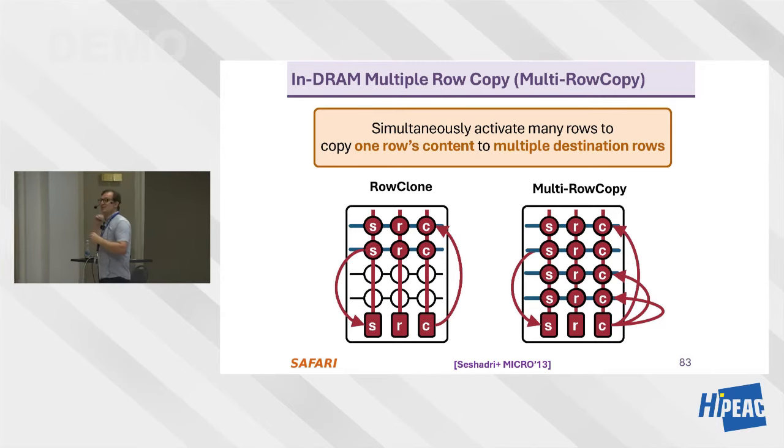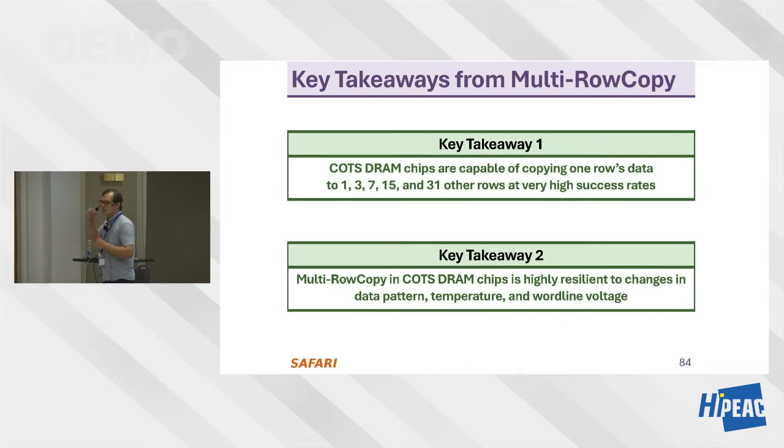So if you can initialize your DRAM very quickly, and you detect this sort of thing, you can get rid of the private data that you don't want to expose to anyone. And we show in this work that this is a very good protection for cold boot attacks, better than existing mechanisms. And it's a lightweight protection. You can of course do encryption, but encryption is a very heavyweight protection for those things, especially in IoT or edge type of systems.